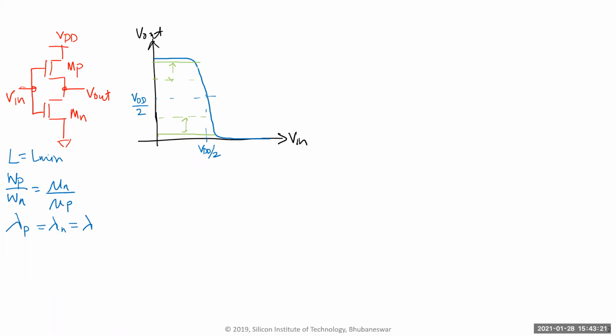But now we are interested in using it as an amplifier. So now if I want to do dV out over dV in, how does it look for V in? It's basically almost 0, and then it goes up and then goes back down, right? And we choose this point. Actually, it's negative, so I should write mod for this. This is a negative curve, so I should write mod for this. So the places where it's 1, those are the noise margin points, right? The NML and NMH is where it's chosen.